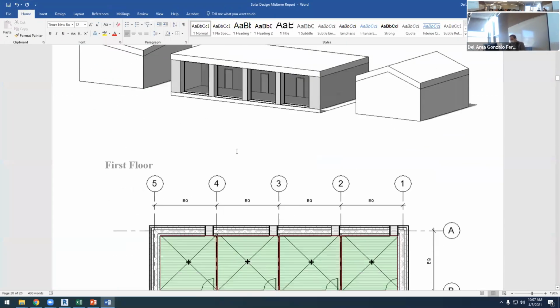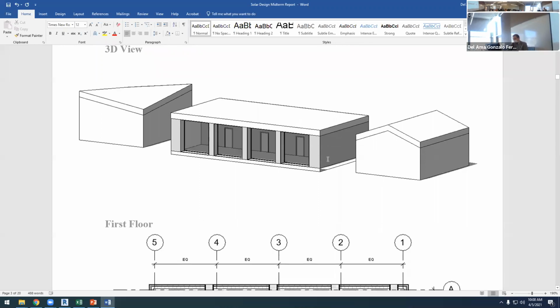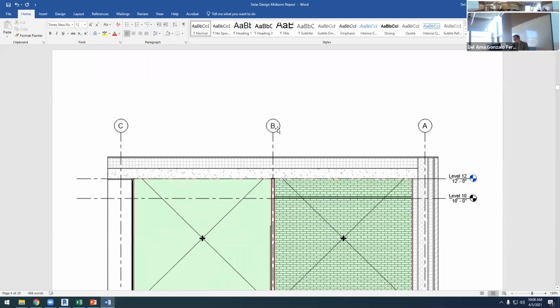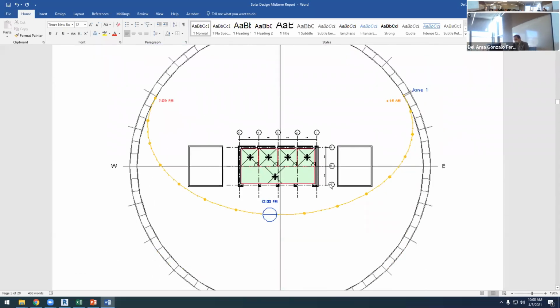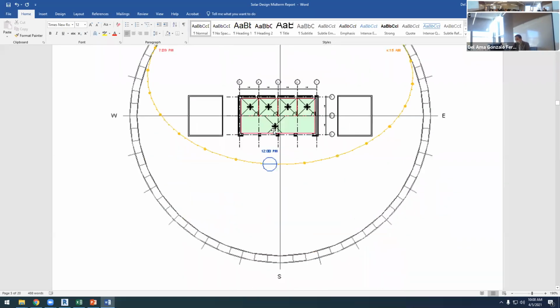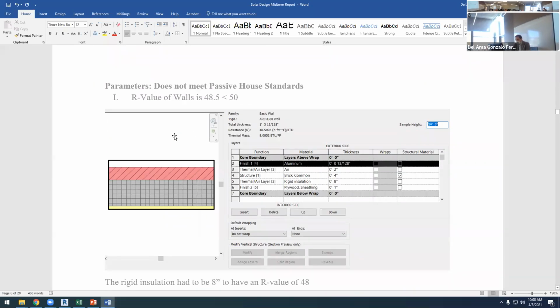But let's go over everything. So yeah, this is what I wanted. We have a building, we have something there. This is the justification. Why don't we have openings here, east and west? Well, because we have buildings, this is too narrow and there is no point in opening this. So that would be the answer. These are the spaces in plan and section. Here we have the sun path because I want to make sure that this is south and north oriented. The energy analysis, here we have all these materials.